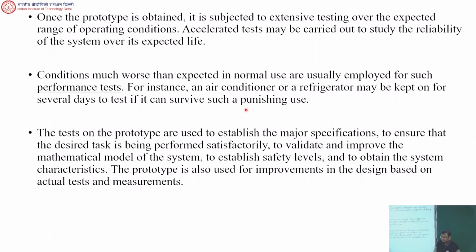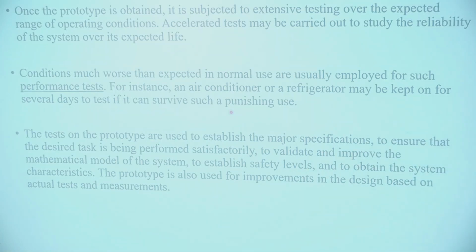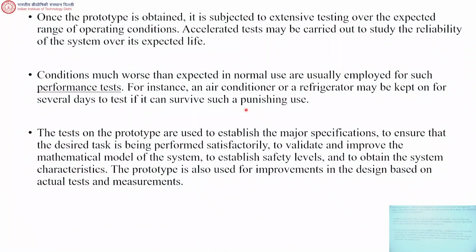But that same fluid is getting heated, cooled and all that. So it's 200 degrees Celsius, then it comes down to 25, again gets heated to 200. So there is a cycling process which takes place, right? Getting heated, getting cooled, again getting heated, getting again cooled. So this thing will, as you can imagine, result in some deterioration of the properties of the fluid. Right? The fluid might not work as well if you use it for maybe several years, or maybe 5 years, 10 years, I don't know, it depends on the particular system.